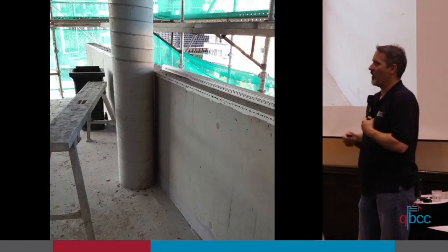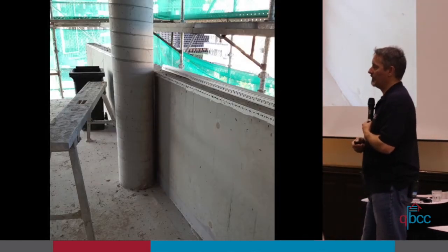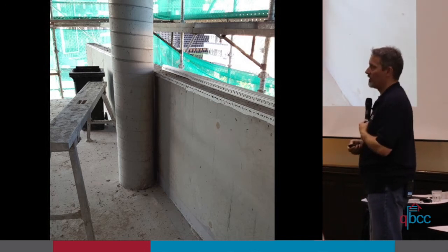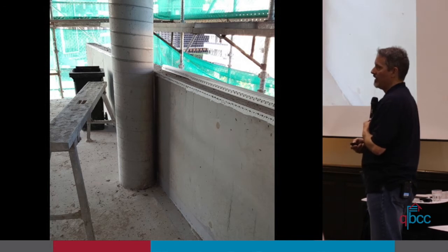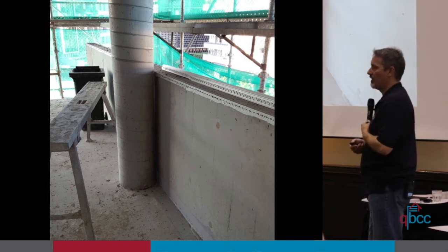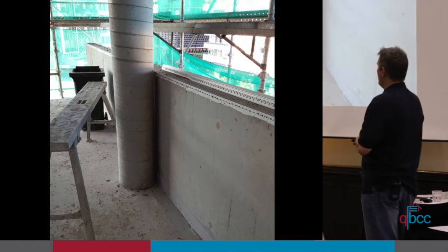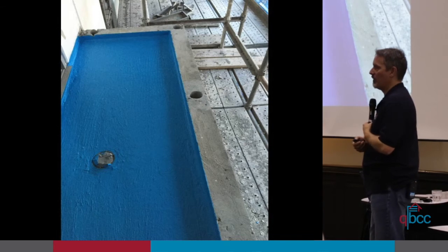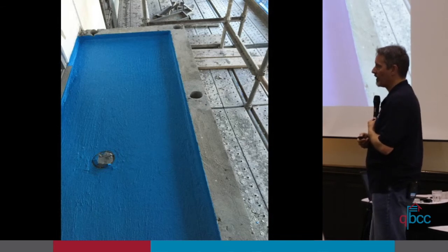The other part of the design is the actual design of the building, right? So waterproofing where that column meets the wall is going to be quite a tricky detail. So the designers of the building have to think ahead of how do we make that area waterproof. And of course, designing the extent of a waterproofing membrane is also very, very important.